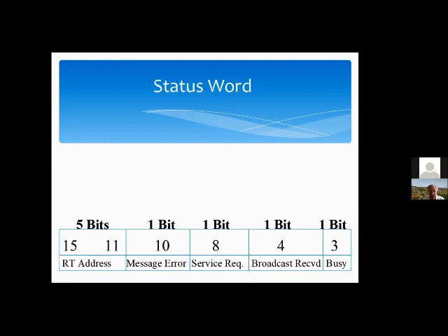And for example, it says that if you want to give an angle, angles are given in semicircles. This is as opposed to, I believe, CAN bus uses radians, and ARINC 429 uses degrees and minutes. So 1553 uses semicircles. Again, it's not part of the spec. So the spec itself says nothing.